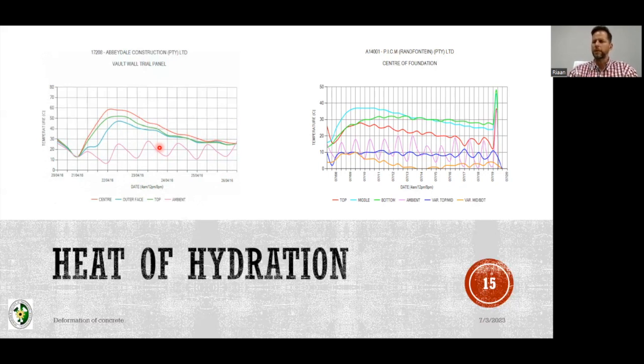we covered it with plastic, and then we put shutterboard on top of the plastic. And the temperature under that board was close to 50 when I went and measured on day 2. Put my thermometer under the plastic, drop the board again, and then wait a few seconds, you got 50 degrees. It was lovely. This is April, it was quite cold.